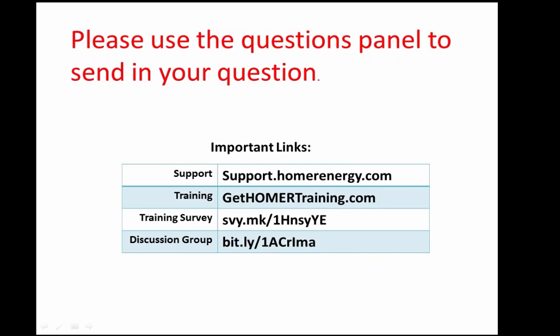Okay. Is it possible to add other costs like buildings, installation cost, wiring, and meters for distribution into your model? Yeah. Under the project button of the system ribbon, there is an option to add in system fixed capital cost and system fixed O&M cost. And that's a good spot to put those sort of costs that are less influenced by the design.